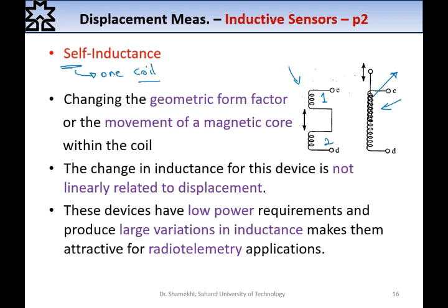The change in inductance for this device is not linearly related to displacement, as you know. These devices have low power requirement and produce large variation in inductance, which makes them attractive for radio telemetry applications, especially in medicine applications.